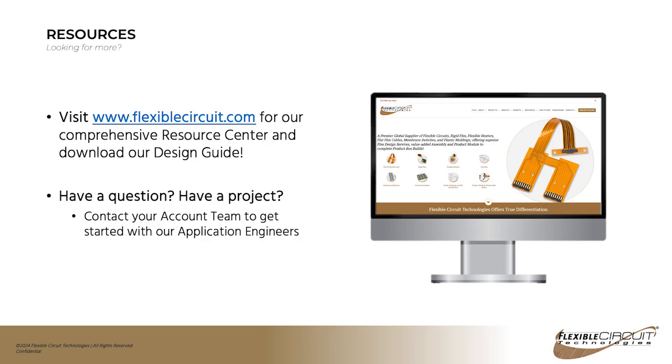For SMT components, you'd want to have a mechanical stiffener, something like FR4 is probably the most common, but we could also use thicker polyimide film to keep the thickness down, but something to rigidize it, because if you bend your flex circuit in areas where you have SMT components, whether it's a connector or other components, you can damage the solder joints. So you want to have some mechanical features in there to keep that from bending. For stiffeners, or for connectors, we typically see FR4 as the main thing that's used.